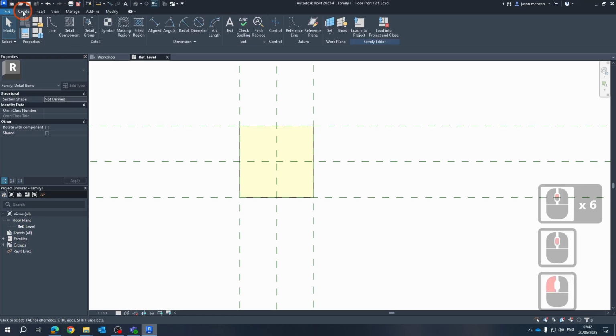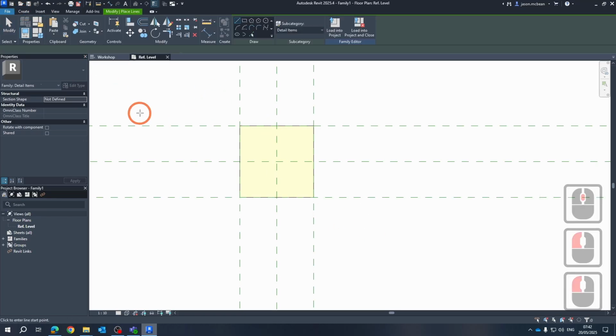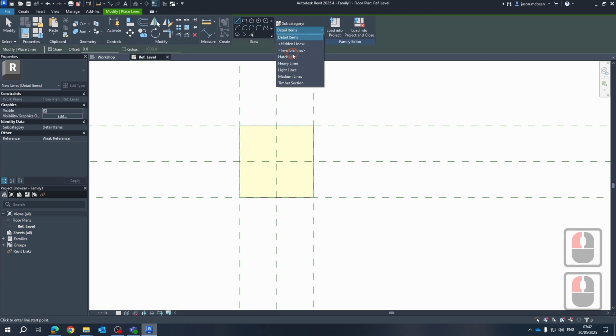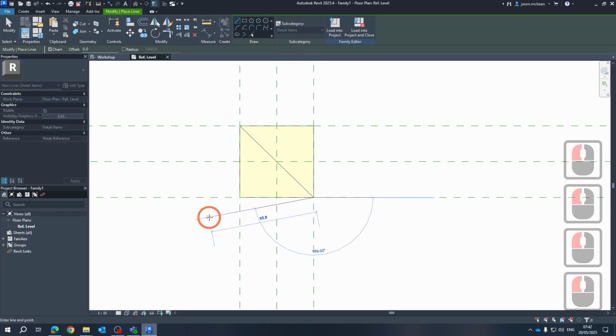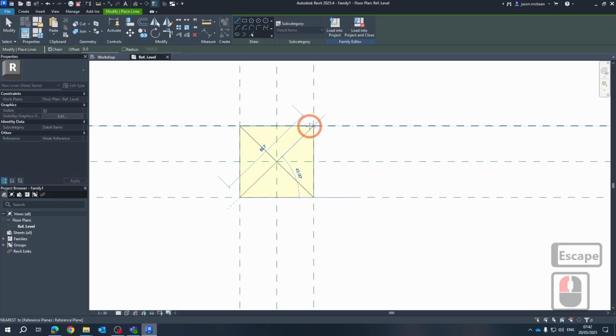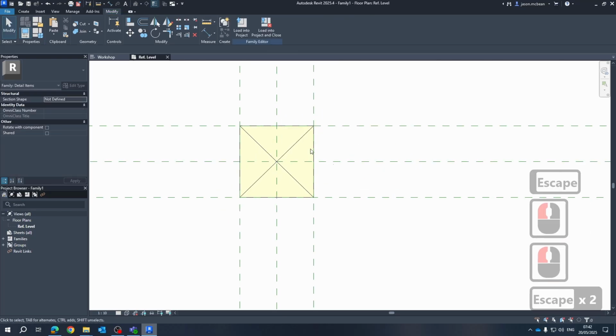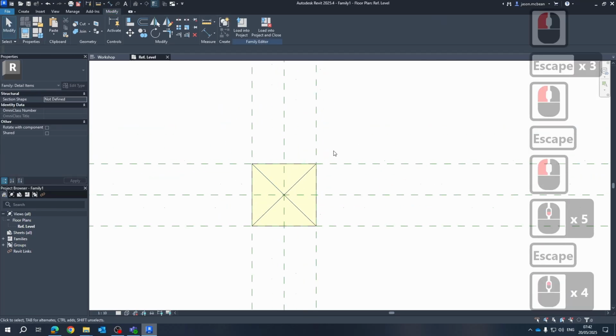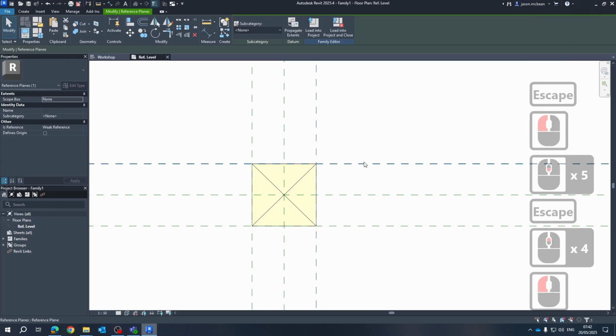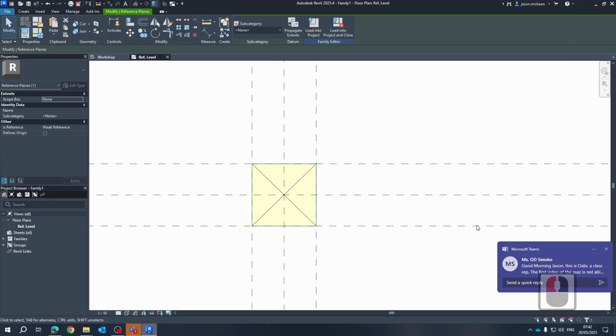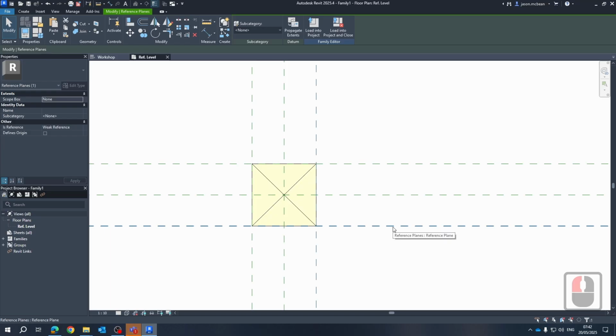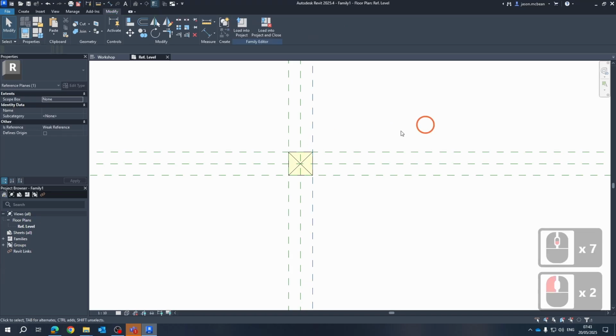The next thing I need to do is to create some detailed line work. So if I go to lines, I need to make 2 hatch lines that go from one diagonal to another. Okay, so one diagonal and another diagonal. Now what's interesting about this line work, it will try and form a relationship. So if you've got reference planes in first, so the goal is set your reference planes up or your constraints up first, and then build your line work over that. If you do it in the opposite order, you will not achieve the desired outcomes. Things won't be hosted and try and form a relationship with the reference planes.